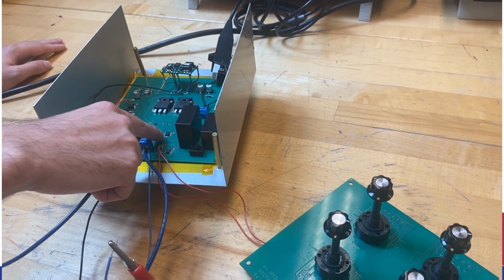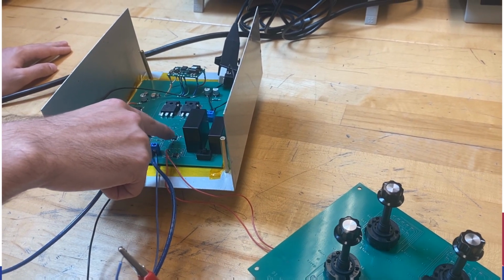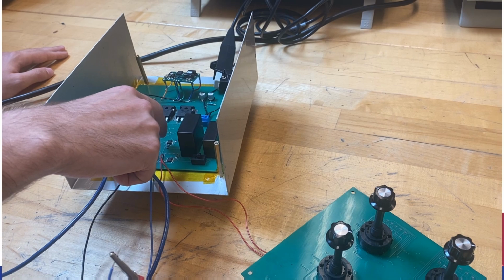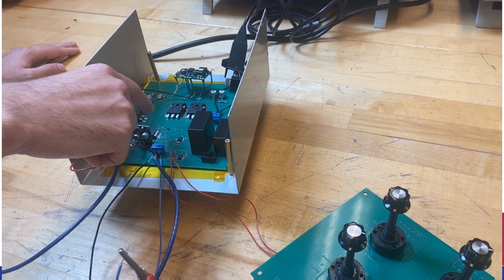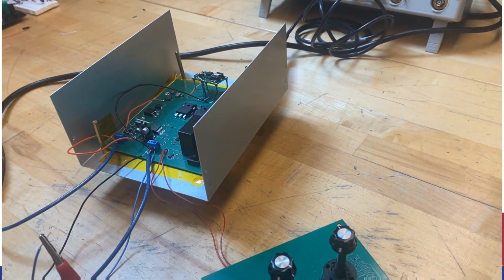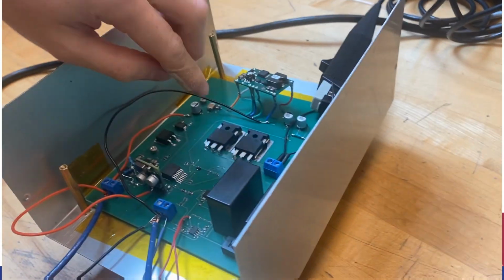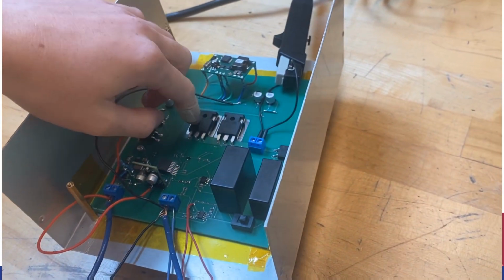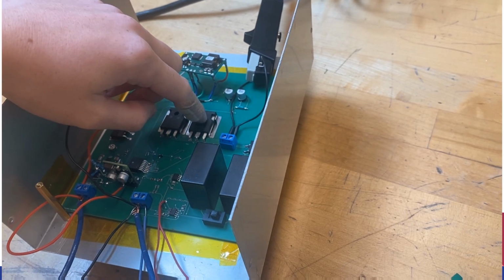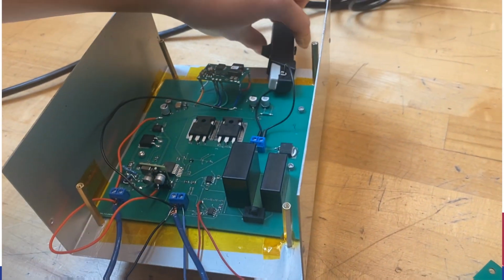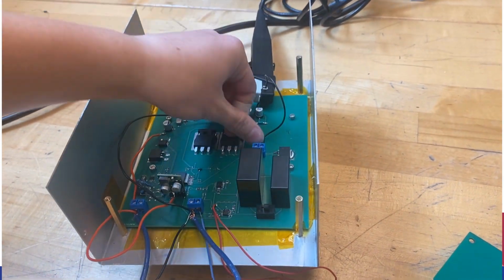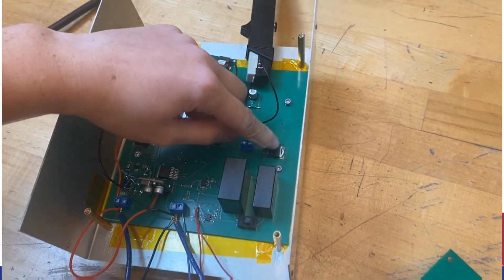And then those feed into this buffer circuit, which just provides infinite impedance, so it can feed safely into the voltage to current converter. For the voltage to current converter, we have our IC here, and we have our two BJTs. This is the PNP and the NPN, and the current probe is attached here to the two terminals, and our load resistor is right there.